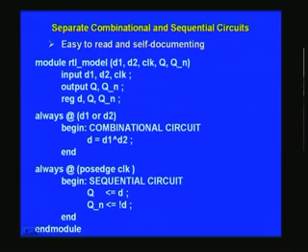And once you have just two blocks, always block. We will come to this statement a little later, and this is an always block which you are once again familiar with. This is just a combinational realization. Whenever D1 or D2 changes, for example, if D1 was 0 earlier, now it changes to 1, or let us say D2 was 1 earlier, now it changes to 0. So only in the event of a change occurring, this will be processed.